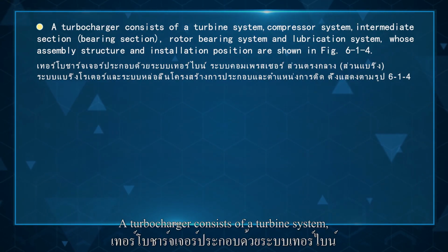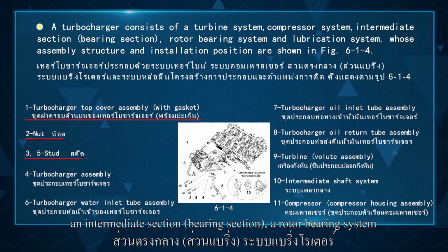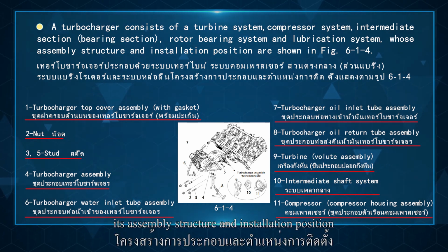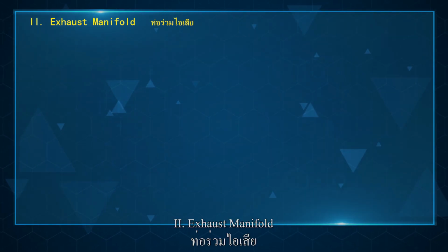A turbocharger consists of a turbine system, a compressor system, an intermediate section, bearing section, a rotor bearing system, and a lubrication system. Its assembly structure and installation position are shown in figure 6.1.4. 2. Exhaust manifold.